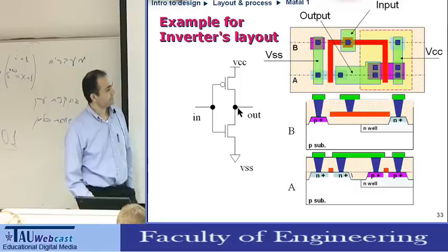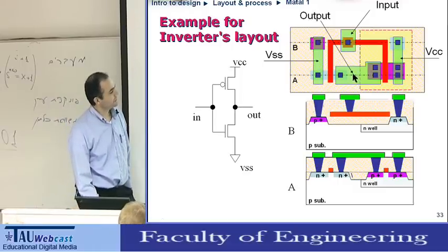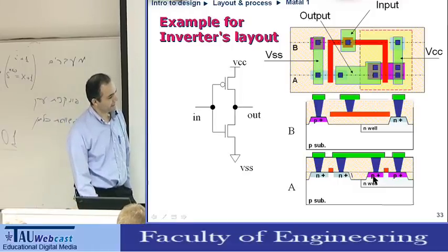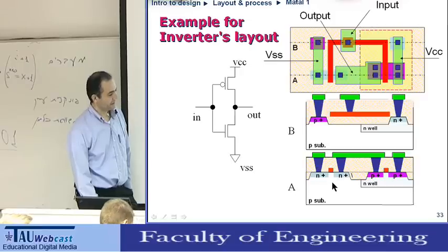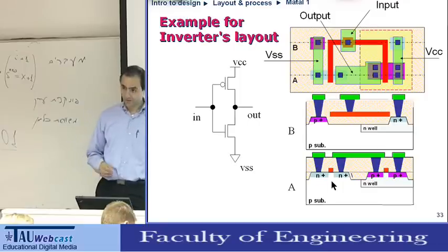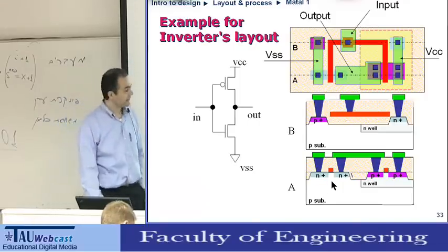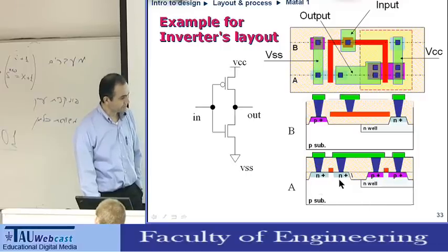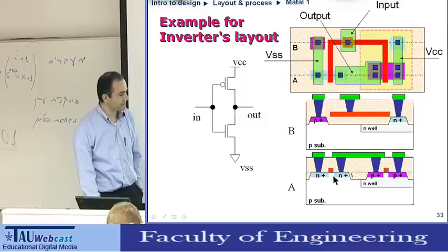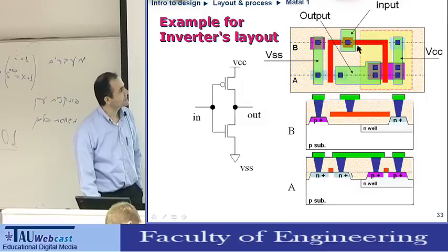And what we can see more is that we have a P plus on N-well. This would be the P-channel transistor. N plus on P-well. Actually, in this inverter, we don't have a P-well because all the substrate is P. So we saved one layer. So this is the substrate, and the P substrate will get an N-channel transistor. So this was this cross-section.